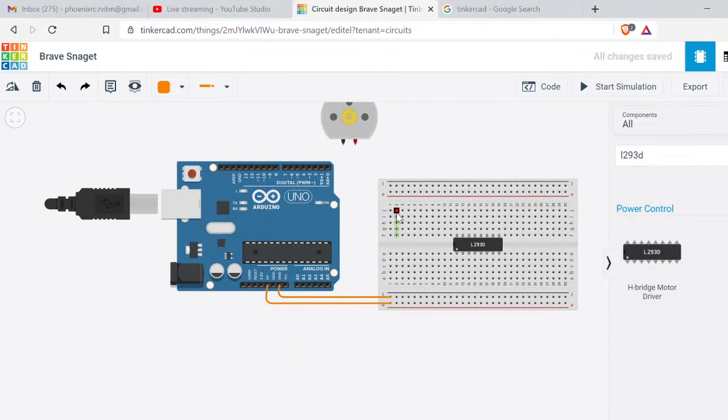Yeah, this is a breadboard. This is the enable pin, and as these all have the same potential, if I connect a wire from here, it will be connected to the enable pin only. If I connect here, it will also be the enable pin only. So first thing, I want to connect the enable pin to 5 volts. I will connect it to 5 volts here. You can connect from here, here, or anywhere, if vertically everything is the same.